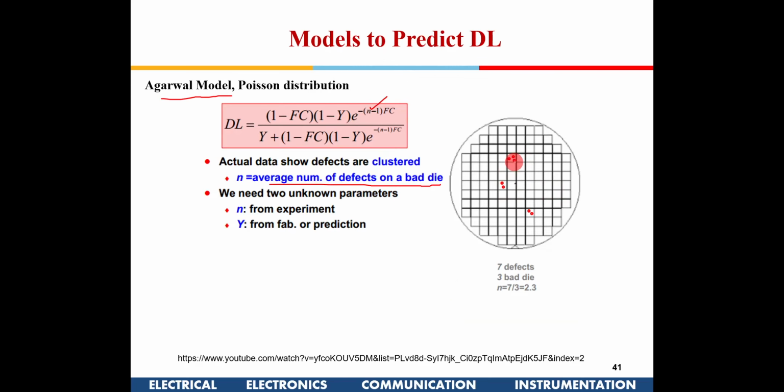So the binomial model is slightly pessimistic, because all the faults are equally divided over all the wafers. If you try to put these three faults in three different places as a binomial distribution, you will probably get a too pessimistic result. But this takes into consideration that there could be multiple faults within the die, and that is generally the case towards these edges. So that aspect is also taken.